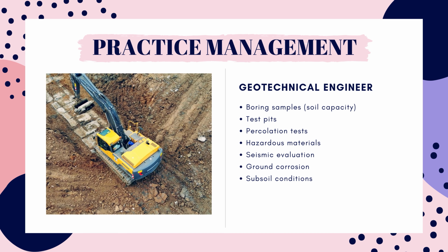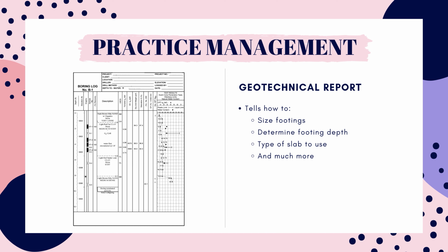This geotechnical report is typically provided by the owner before design starts or in the very early stages of design. We use this to see where to place the building on the site, and the structural engineer will use this information to size the footings, determine the footing depth, and the type of slab to use. So it's very important that we get this report early on in the project.